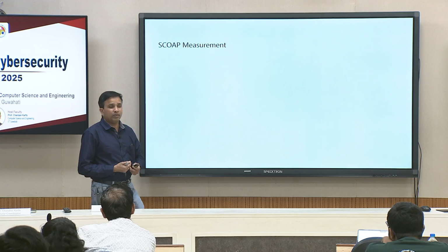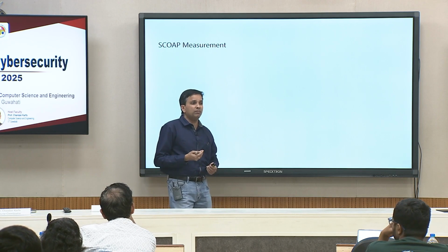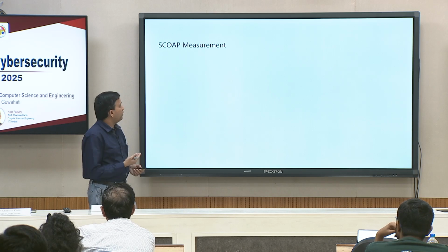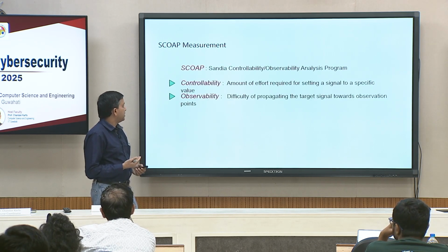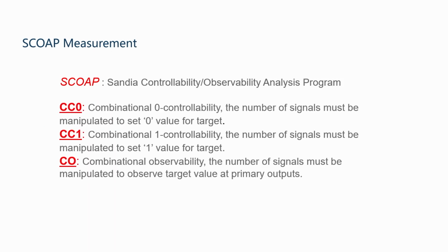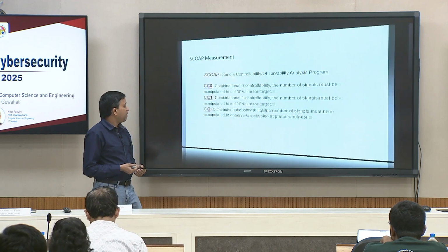The metric is basically SCOAP. So, basically the values or the signals: for a specific bit flip, did it make something more controllable or less controllable, more observable or less observable. All that metric we computed using one of the open source libraries called SCOAP, and it has a lot of internal details, different values it gives, and you make use of that to compute whether to reward or keep the flip, or whether to penalize or undo the flip.